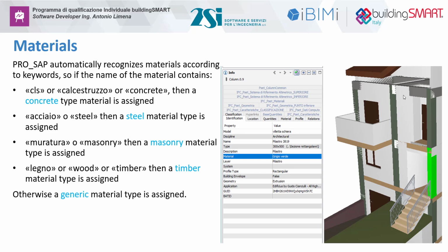That is a color, and of course this helps the architect in moving through the model using some sort of order that is only in his mind. So it's not generic, it is not global. It doesn't mean the same thing for everyone who opens the file. So it is better to use correct names for each material and not color names or improper names like this example.